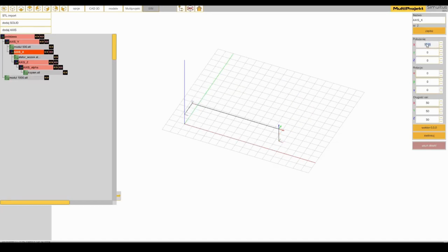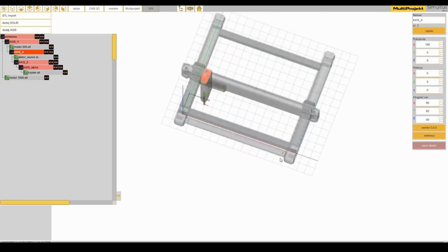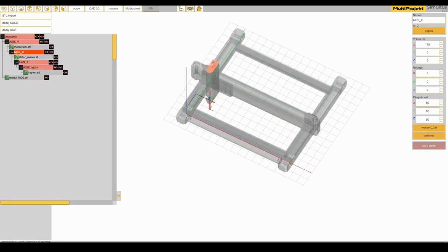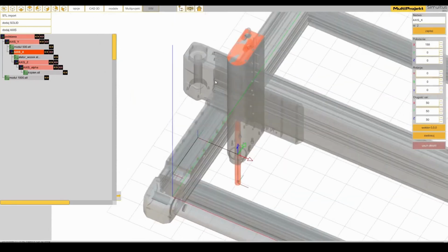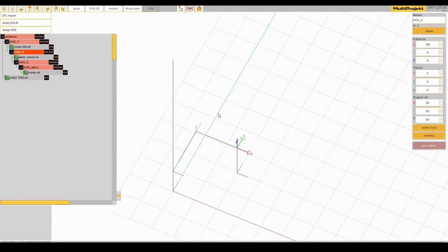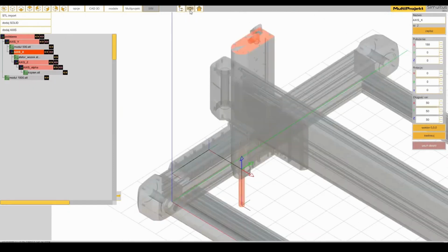Let's move the x-axis by 1000 mm in the negative direction. Naturally, we can set any other starting position. Along with the x-axis system, all the elements connected to it have moved. Both other coordinate systems and all mechanical elements as well. Referring to what we talked about a moment earlier in this part of the training, we simply change the initial settings of our coordinate system.